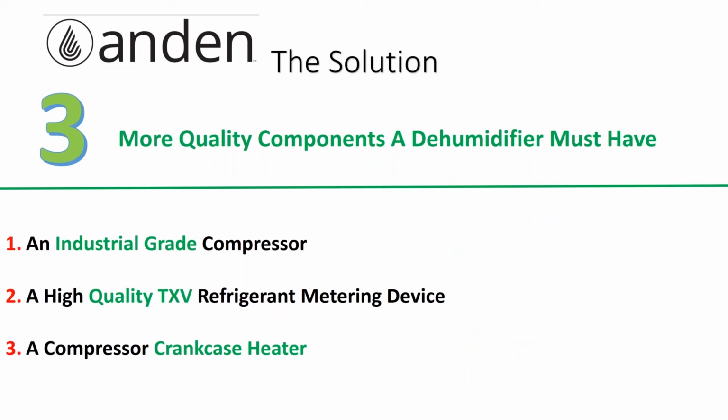There is a way to manage this, and it comes with designing a dehumidifier that was designed to modulate as temperatures modulate. You're never going to prevent a dehumidifier from losing capacity as temperature changes. It's just physics. But you can change the rate at which the capacity drops. More importantly, if you do it the right way, you can increase the amount of dehumidification at certain temperatures that are tuned in with agriculture, which is exactly what we did.